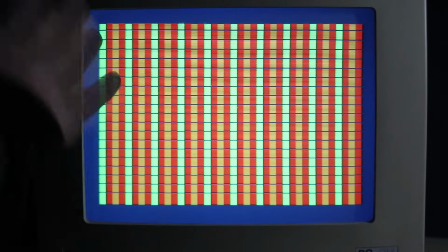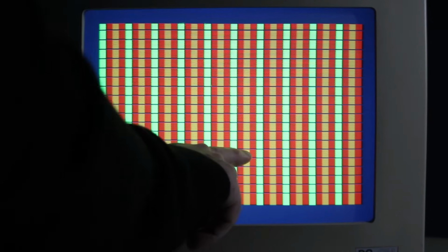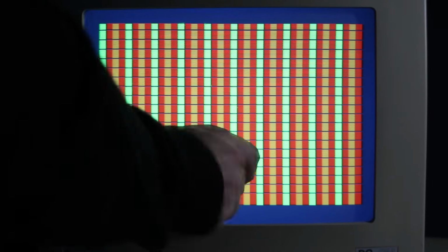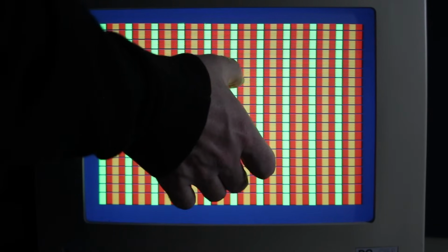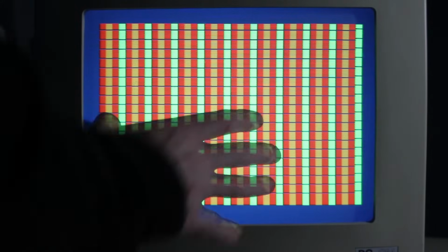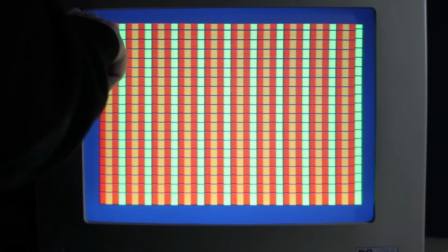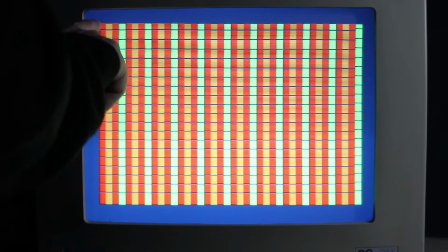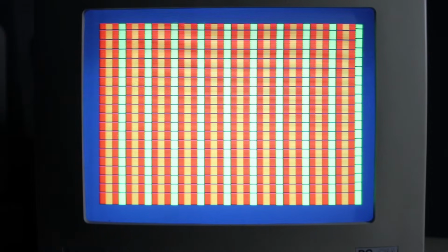on the screen. So this program is just like the other ones that we've seen already. It makes one change here and then changes the value back down here. So I'd hoped that we'd get something weird happening just in a certain portion of the screen. But let me show you what actually happens. You can see everything just sort of shifted left by one character, and that's because it started reading from video RAM one character later than it otherwise would.